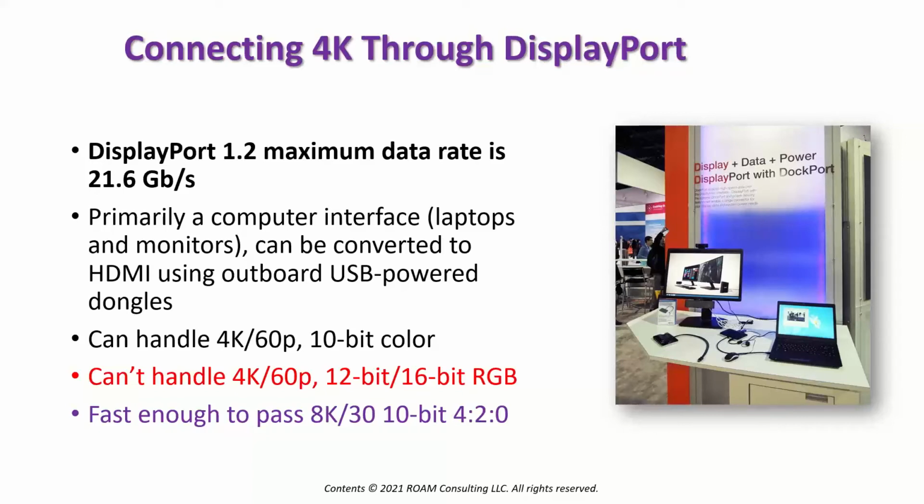The computer guys say HDMI is a TV interface, although you are starting to see more computers that support HDMI. The beauty of DisplayPort is you can convert it easily to HDMI because DisplayPort carries a small amount of power on one of the pins. You can build a converter right into it, and you can plug a cable in and get HDMI out of a DisplayPort connection. Not so easy to do it the other way.